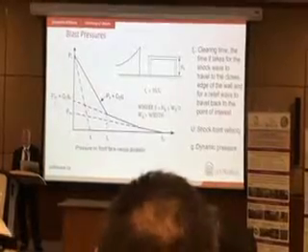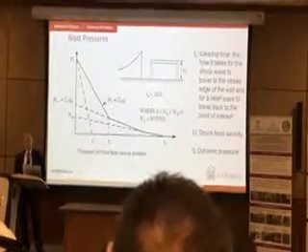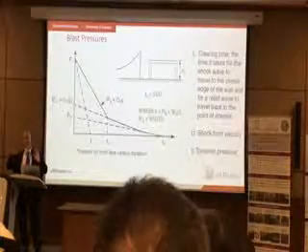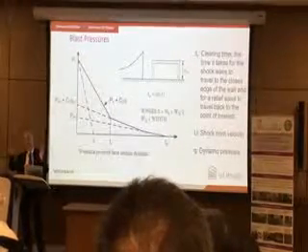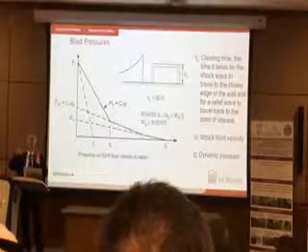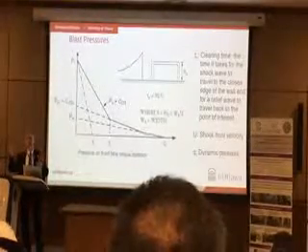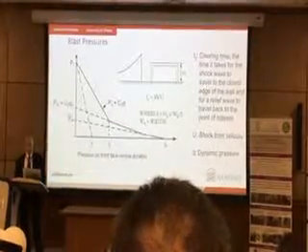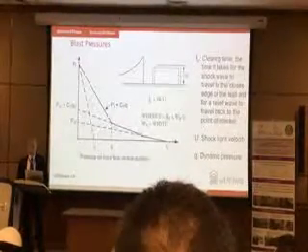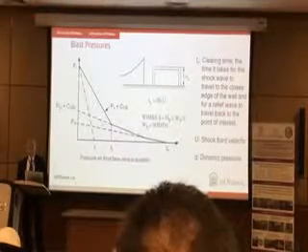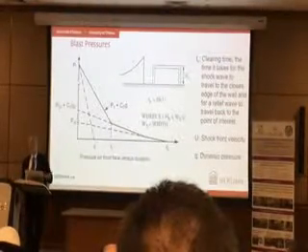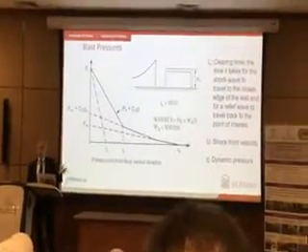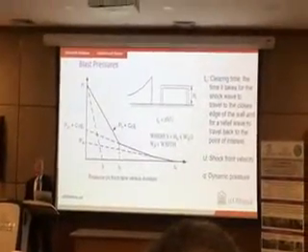But then the other pressure, which is this pressure plus the drag effect, because when the gas pressure comes, it engulfs the building. Depending on whether it's a circular building, square building, there's drag coefficient. So drag forces are generated, it amplifies a little bit, and then it starts coming down. So this shape can be used to more accurately idealize the hyperbolic pressure-time relationship.